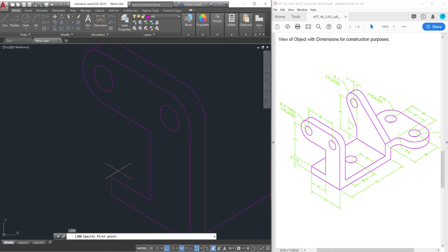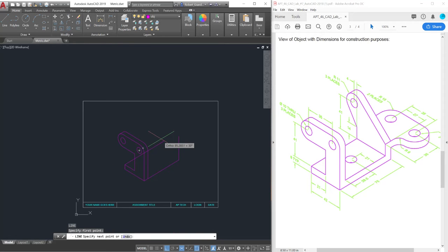And then I'll just finish a little more work here and draw this back this way. So in terms of what I'm going to do here for this back line, I know that the distance here is 75 from this front surface to this back surface. And if this is 8 everywhere for all of the thicknesses on here, I want to go backwards 75 millimeters minus 8, which would make it 68.